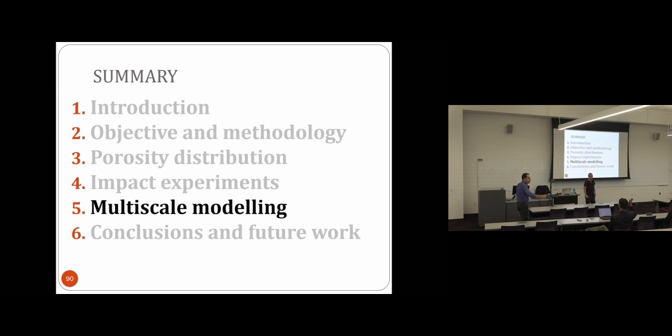Okay, go ahead. Was there any possibility to measure the temperature inside the shear bands or anywhere? A lot of papers show adiabatic heating and liquefaction also happening. Yeah, it is possible, but I don't have the equipment for that. But a priori, it is possible. You can use infrared detectors. Danny Rittel at the Technion is using infrared detectors to do something like this. So yes, it is possible.